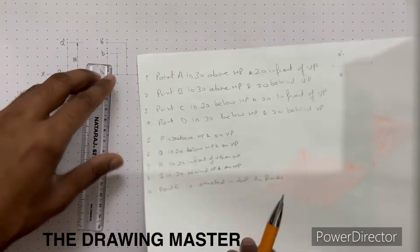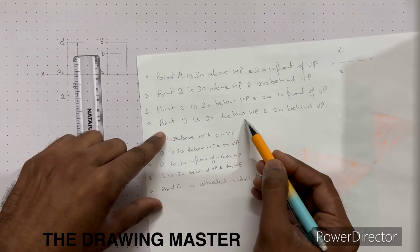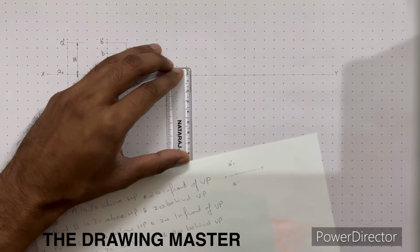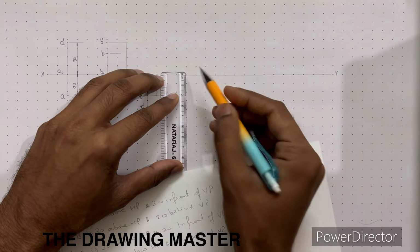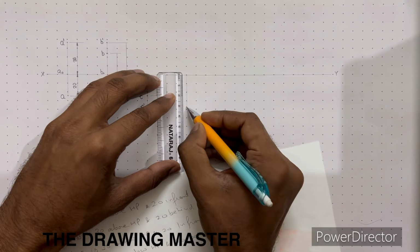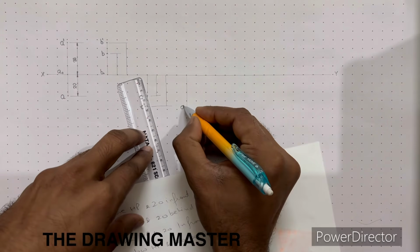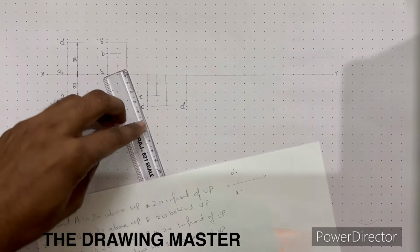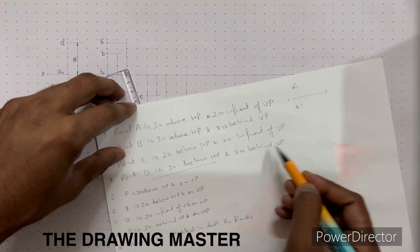Fourth problem is point D is 30 below HP. Okay. Below HP means below the reference line. Above and below is always front view. So this is D dash. Further it is given that point D is 30 below HP and 20 behind VP.